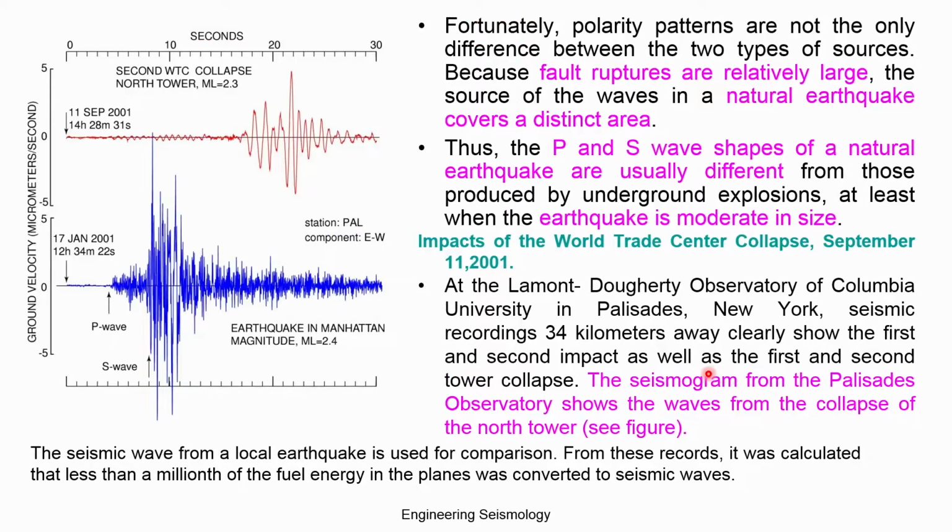We also discussed how to distinguish a real earthquake from the impact due to an explosion, with reference to the Twin Tower blast record in the USA. This is a typical earthquake waveform record. You can see the 2.54 magnitude earthquake at Manhattan. At the same place, there is the twin tower nearby, and the same station recorded the impact of the twin tower at the blasting time.